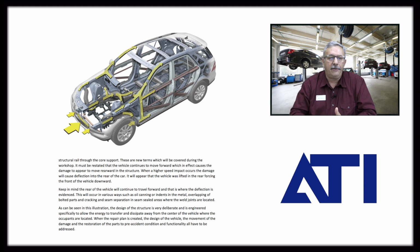Again, I just want to reiterate some of the things that you'll visually be able to see: oil canning or indents in the metal, overlapping of non-bolted to bolted parts, or even in a four-door situation, bolted over bolted parts. Look for cracked seam sealer, any kind of seam separation.